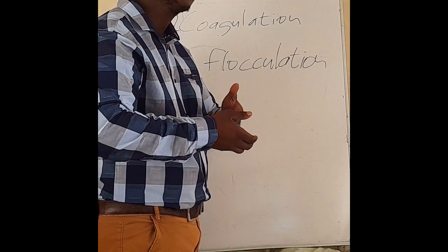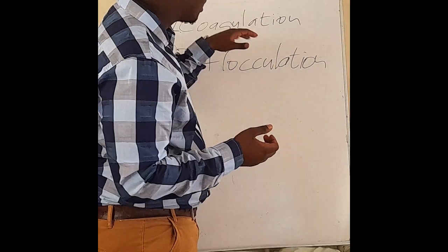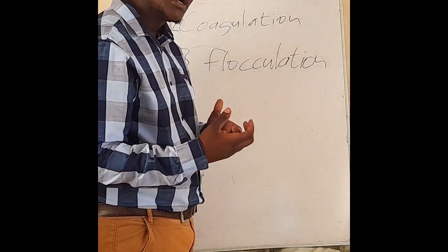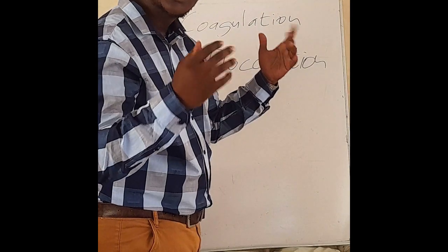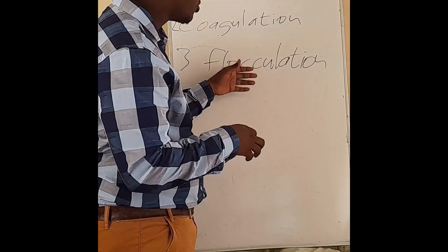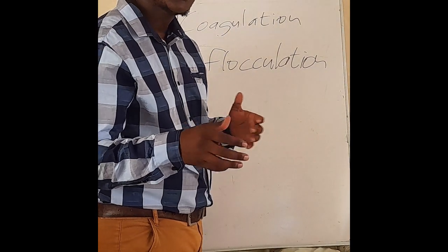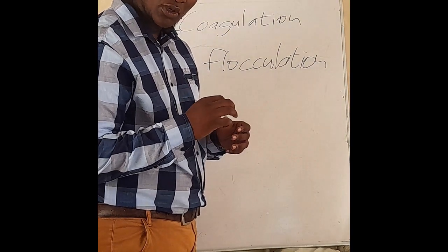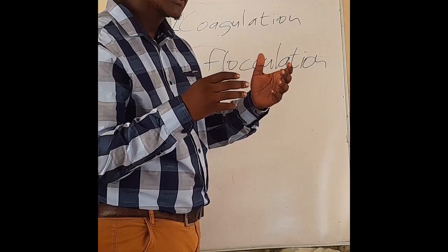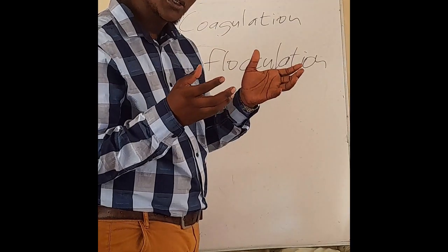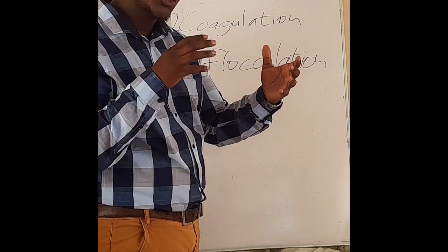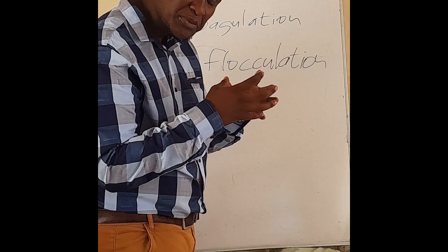Basically there were suspended solids under our coagulation, but because of the chemical that was added, now those suspended solids are able to come together, they clump together, and that's possible under flocculation because now the velocity is very slow in terms of rotation, and since we had used the coagulant aid, they're able to attract each other, they're able to clump up together.